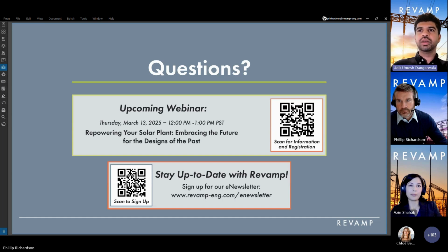I see a question regarding arc flash and the IEEE standard. Why is IEEE 1584/2018 used and not the 2022 standard? So essentially, the methodology is still provided in the 2018 version. 2022 is more of a guidance document on how to implement that methodology. So the basis of the standard and the calculations and the considerations are still provided within the 2018 standard. That's why that was referenced in this presentation.